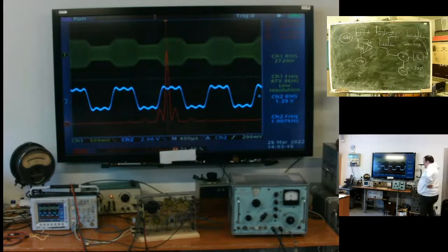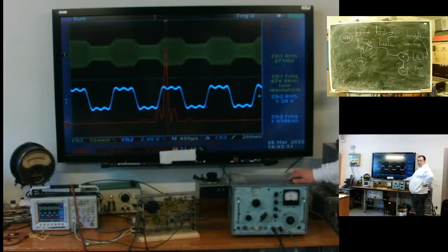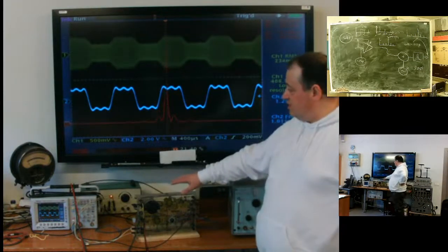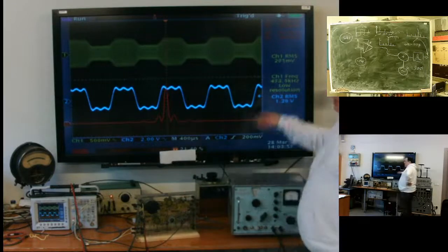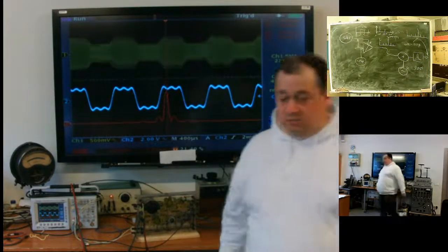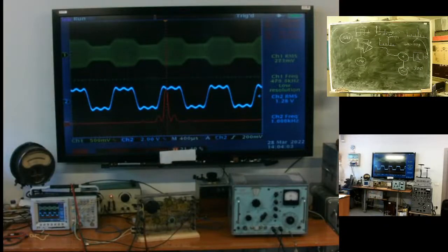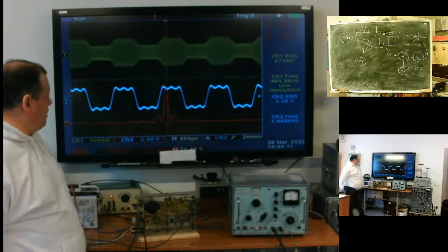One kilohertz, let's say broadcasted at 1 megahertz, with the help of heterodyne, transferred to 400 kilohertz. Here, at 400, we can apply a good selective filter and the result demodulate to get the information back.